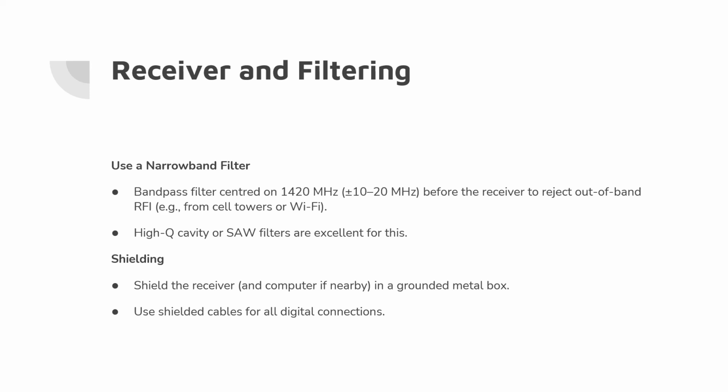Shielding the receiver and computer to try and prevent RFI from your own systems. I think we'd all agree that was definitely a good idea, but the question is, how important is it? Particularly when you get software like Ted's Easy Radio Astronomy, which seems to do an extremely good job of taking a lot of the RFI out.